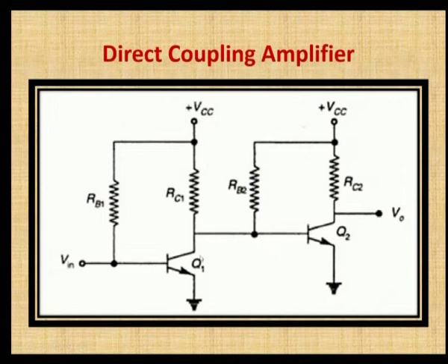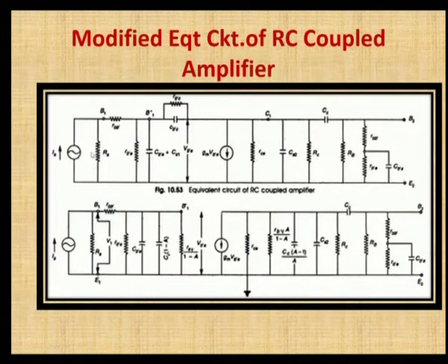Normally an RC coupled amplifier is used in practice. We are going to see about the RC coupled amplifier and its frequency response. If you want to study the frequency response, you have to give the low frequency signal, mid frequency signal and the high frequency signal. So you have to increase the signal's frequency from the lower range to the higher range, and you have to study the gain of the amplifier in all the frequency ranges.